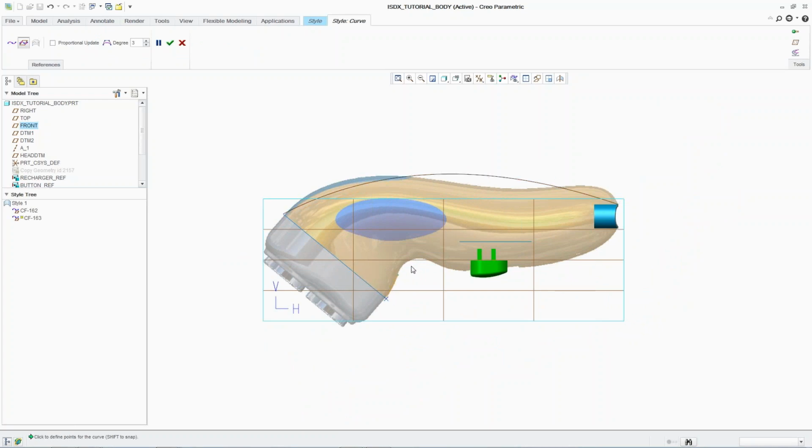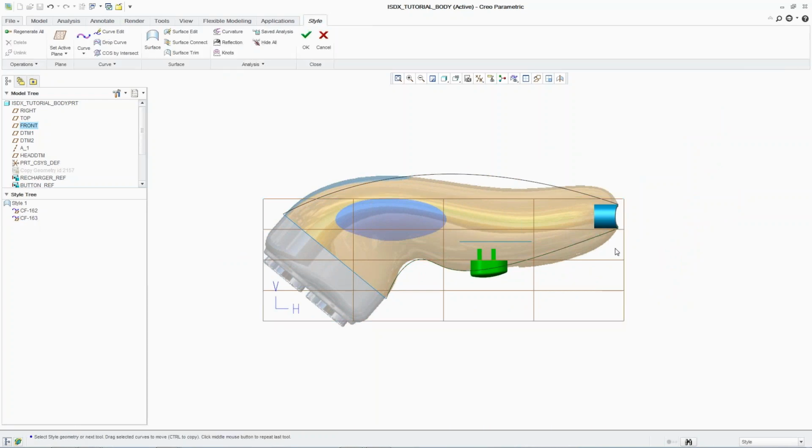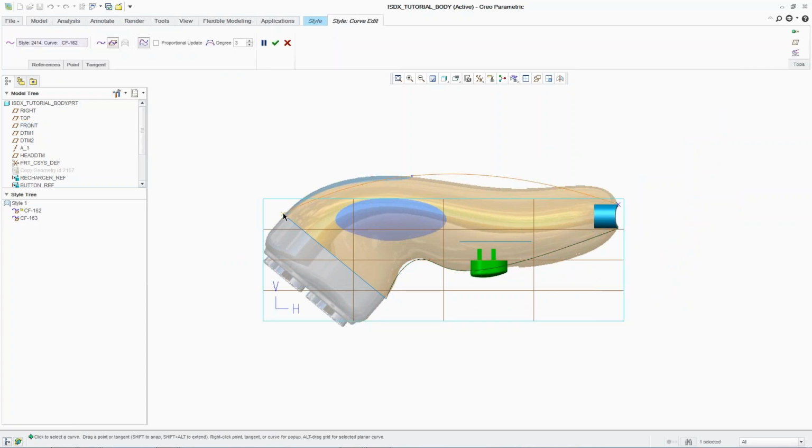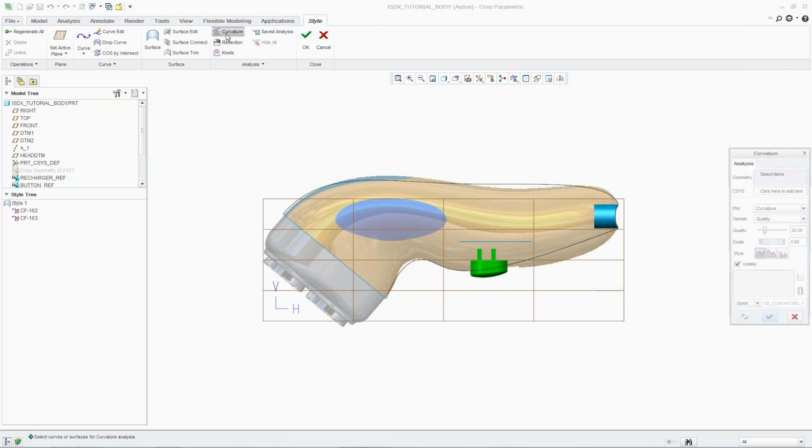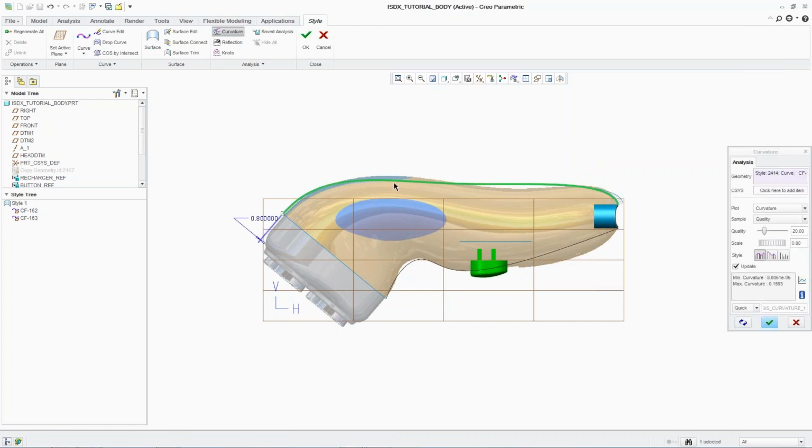It doesn't matter that it doesn't look exactly right at this moment, because we can always go through and manipulate these curves in different ways a little bit further down the road. For instance, at each endpoint, for all those different points that I select in my curve, I can select how they're all going to work together. It's going to be a very hard control. Do I want this edge exactly normal to this plane? Do I want this to be tangent in this area? Or I can just freely drag that to achieve the same purpose.